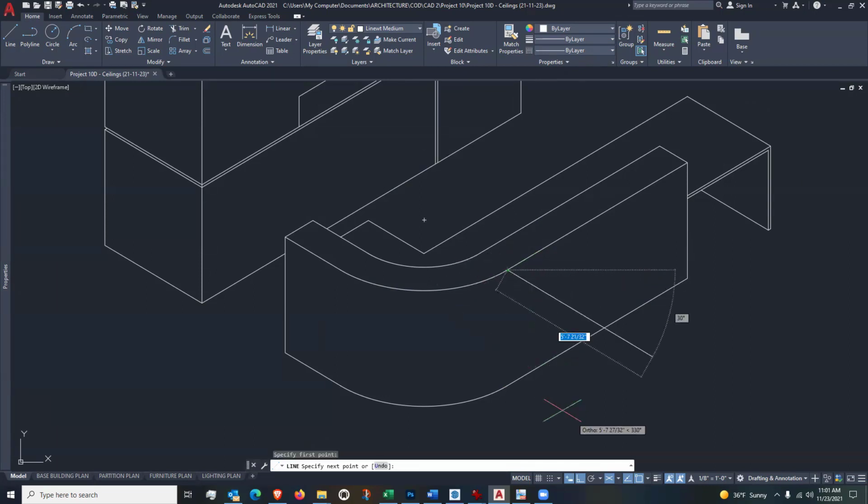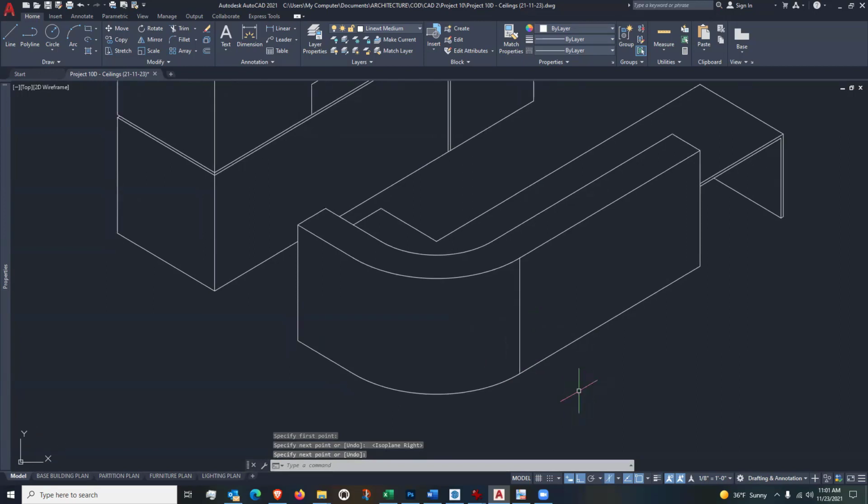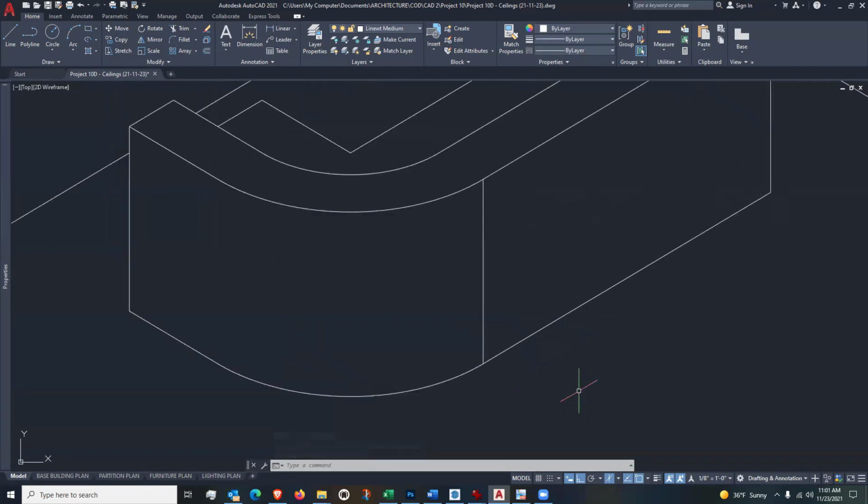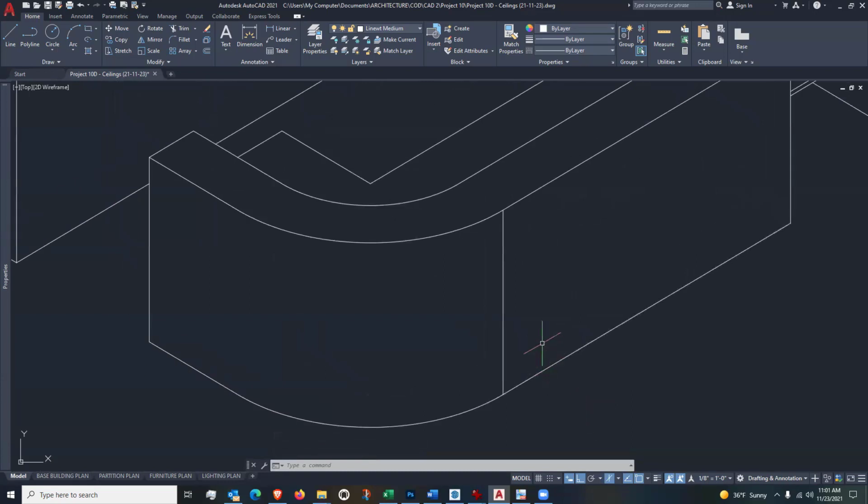So let me go to my line tool, and I'll find that endpoint right there. And oh, lo and behold, I can't draw down. So I'll just hit my F5 until I can. I'll just come down to there. So that'll be the left edge of that reglet. And then I just need to copy it over an inch. So I'll offset. I need to come over 1 inch.